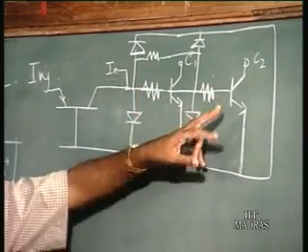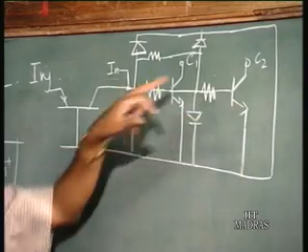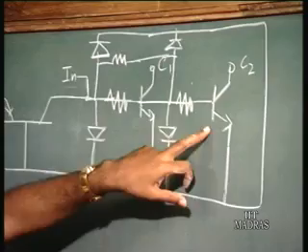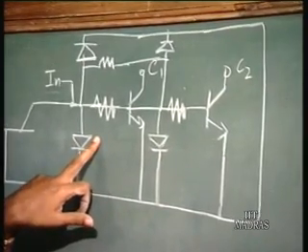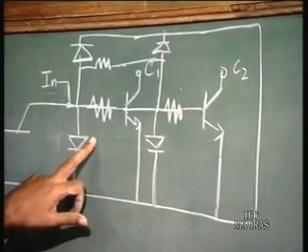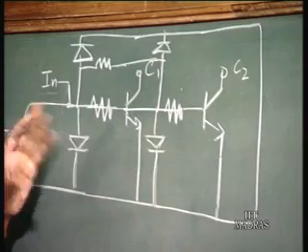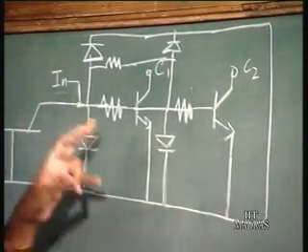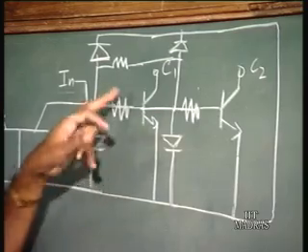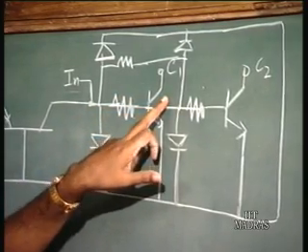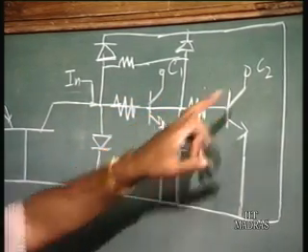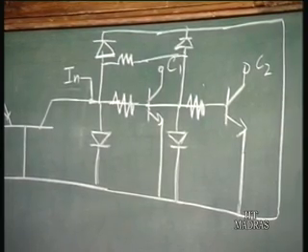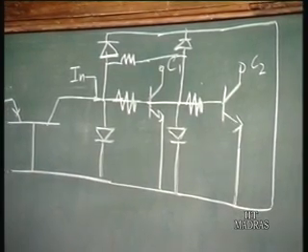But you see that this transistor is not going to behave in a similar fashion as this transistor. It is going to have less base current compared to this transistor. So even though our analysis says it should work, it may not work because this collector C1 may go to saturation, but the other transistor may not go to saturation. So this could be the problem.